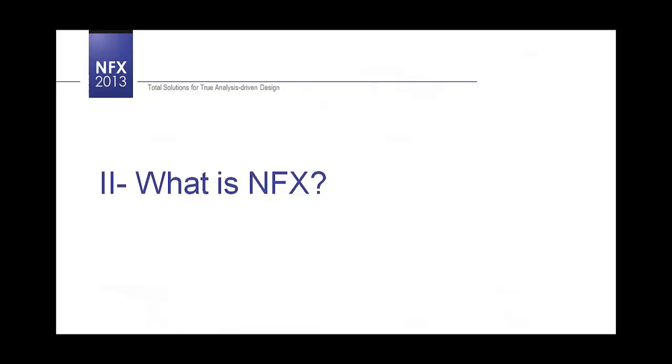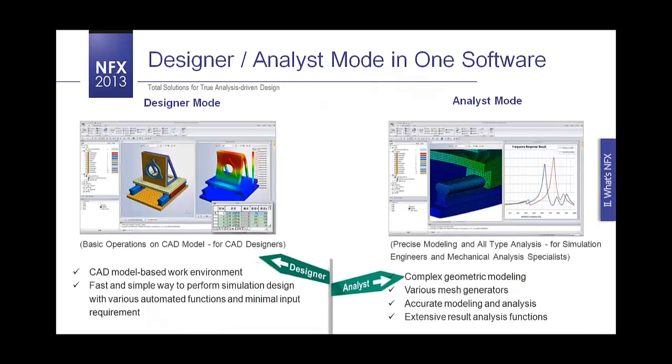So what is really Midas NFX? Midas NFX provides first two modes which are made for the two types of workflow I just described. One is the designer mode and the other one is the analyst mode. Designer mode helps the designer to perform very quickly any type of simple analysis, whereas the analyst mode provides all the features of the high-end software, the manual meshing of any type. It can be 1D, 2D, 3D mesh, any type of analysis, everything.